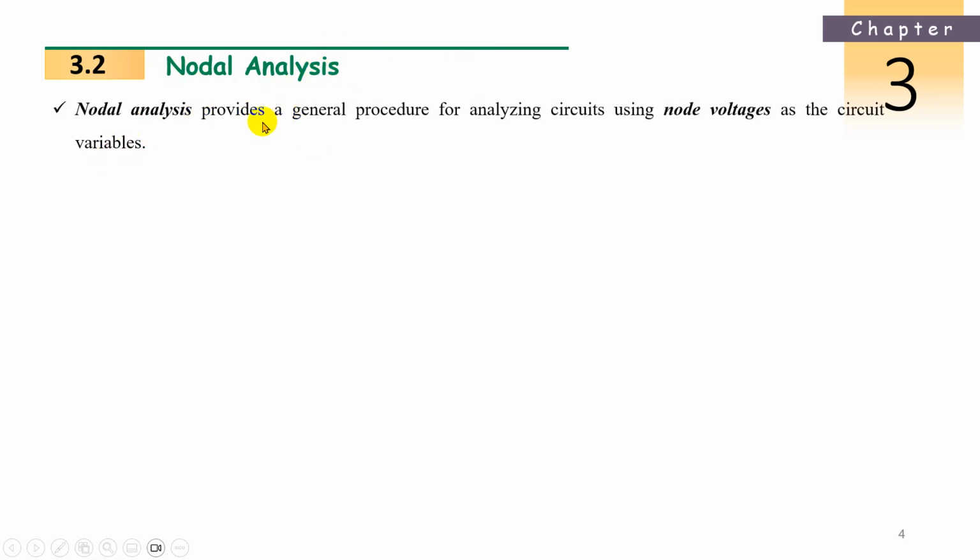So what is node analysis? Node analysis provides a general procedure for analyzing circuits using node voltages. Generally at a node, what will be there? The sum of currents entering equals the sum of currents leaving. So this is one equation. In this equation, remove the current and put in the voltage equation. I equals what? Ohm's law, V by R.